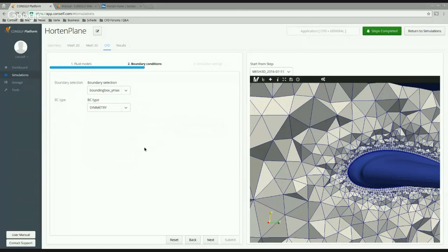Okay, and finally, Z minus and Z maximum. Well, the flow enters from the Z minus, and in this case, we have to apply an inlet because the flow enters from there, and we will assign the velocity. In this case, we use 100 meters per second, and here you have to prescribe the hydraulic diameter, that in this case can be used around 25. It's a length and is linked with the dimension of your inlet boundaries.